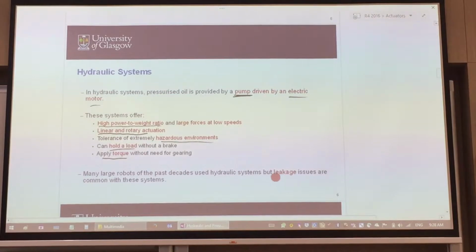There are more leakage issues associated with the hydraulic system. In fact, I visited the hydraulic lab, and once you step in, you get to smell the hydraulic oil. That's because they need to do the maintenance work. And on the floor, you get oil drip stains. So it's actually a very dirty environment when you start using hydraulics. You definitely get leakages because of the high pressure.